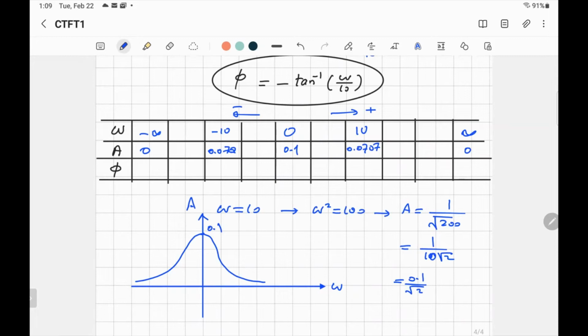Do you know what a pass filter means? The filter allows certain frequencies to pass and decreases the rest. You know what I mean? So this one, which frequency will pass? It has high magnitude. It is 0.1 at 0, which means at DC. And every time you look at the frequency, when it's low, the amplitude is high. But when you go to high frequency, it's almost 0. So it's getting rid of the high frequency and leaving only the low frequency.